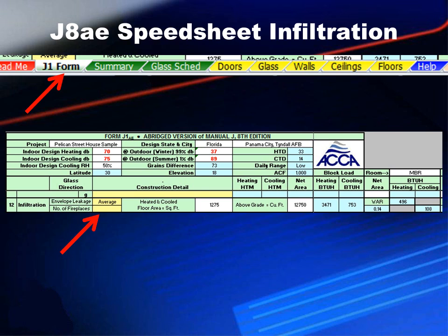And in older homes, you probably want to use loose. You don't want to use average. Most homes, if they're really well built and they've got wraps on them and have been done to new standards, end up being average when you do a blower door test on them, unless somebody's done a whole lot of time and money trying to seal them up tighter.